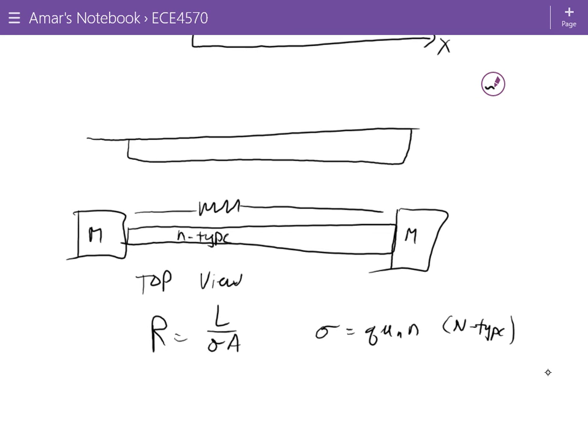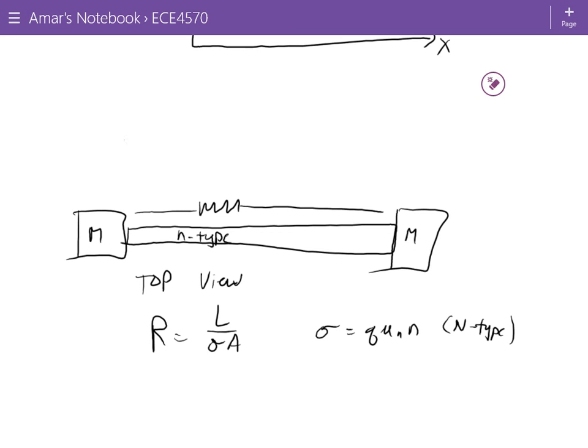What we're trying to do right now is find the resistance of the channel in the case of the MOSFET. We cannot use this simple formula, and the reason is that we have a situation where this part of the channel, this sigma here, is different than the sigma on the right side of the channel. The sigma is changing as we go through the length of the channel. So you can't just use a simple formula to do it. You actually have to use an integral.